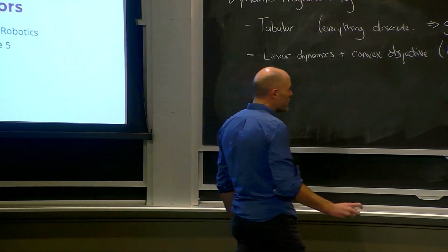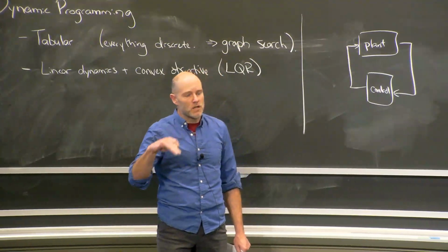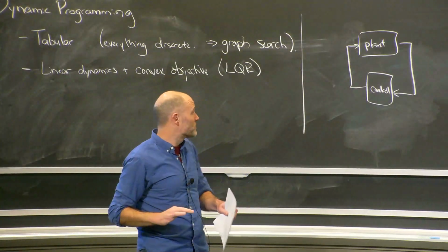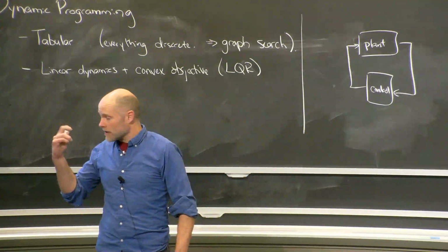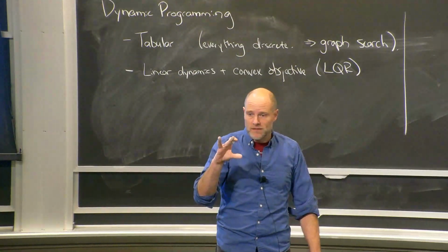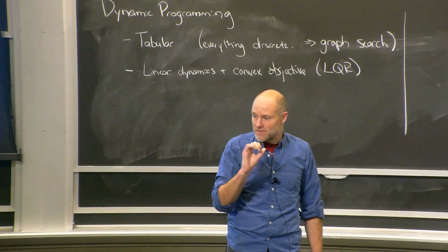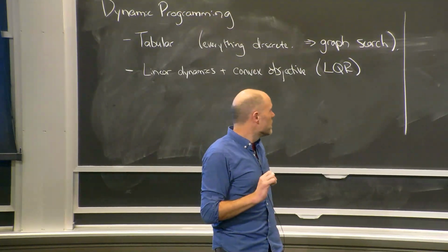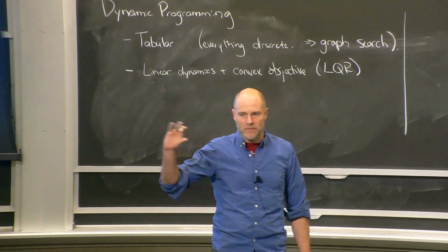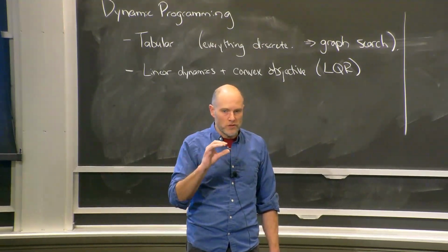That's how you build complicated dynamics equations. The thing that's most unique about Drake is that even when you compose different dynamical systems together, like I always talk about, and we'll talk about it again today, the plant is not just a black box. It's got the manipulator equations inside it. They have certain structure. The mass matrix is positive definite, all these things. Okay. Let's say you're going to use the physics engine, but you want to put in some aerodynamic forces, or like a propeller or a wing or something like this. These all have certain structures.